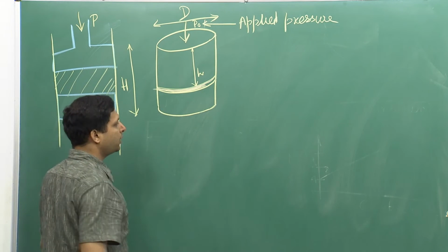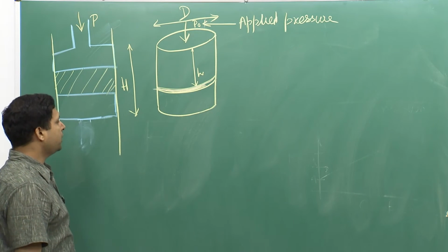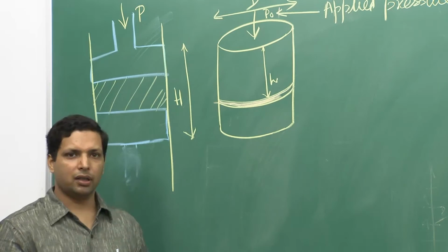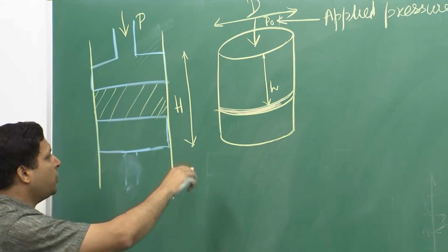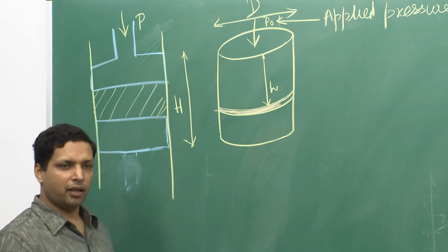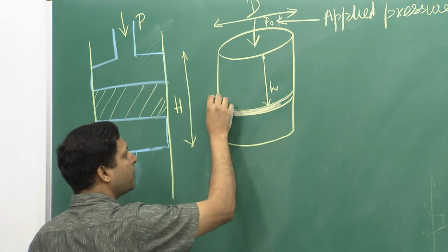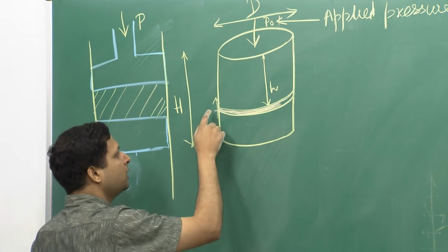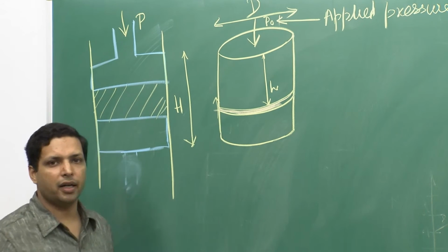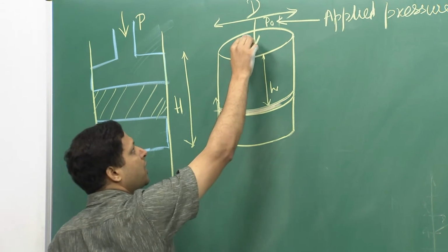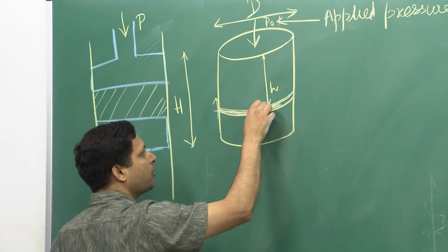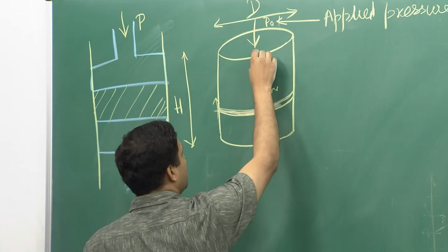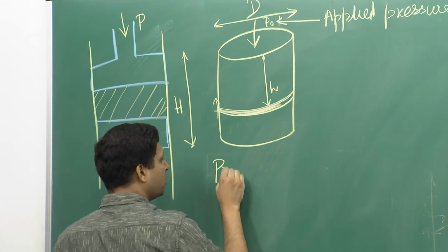Now, what we want to understand is that this whole thing is inside a cylinder or some kind of piston. When you are applying pressure, these things are moving, and if there is some amount of friction, then this friction will act in the opposite direction. The particulates are moving in this direction and the forces act in the other direction, and because of that the pressure being applied here would not be the same as the pressure being applied here. In general, you would see that the pressure drops continuously; there will be a pressure gradient.